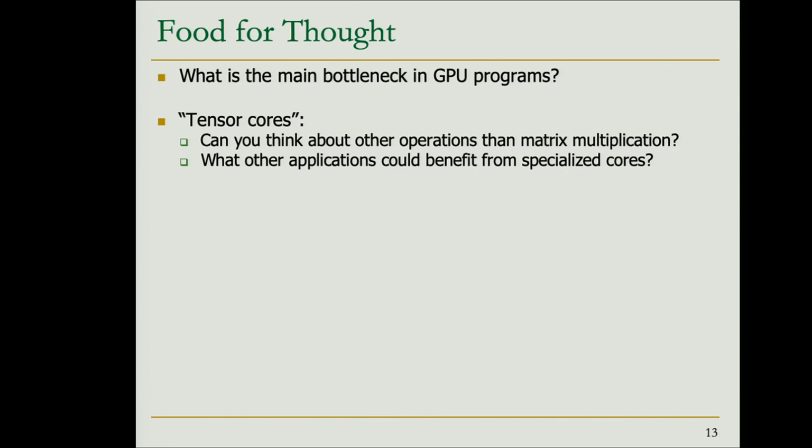And the question here is, is it possible to use these tensor cores, which are super fast and very nice, for other applications? This is something that some people are exploring these days, trying to see how to slightly modify these tensor cores in order to be able to do more computation. For example, there is a very recent proposal in MICRO 2019 about utilizing these tensor cores to execute sparse matrix computations as well, which is going to be more and more important for neural network training.